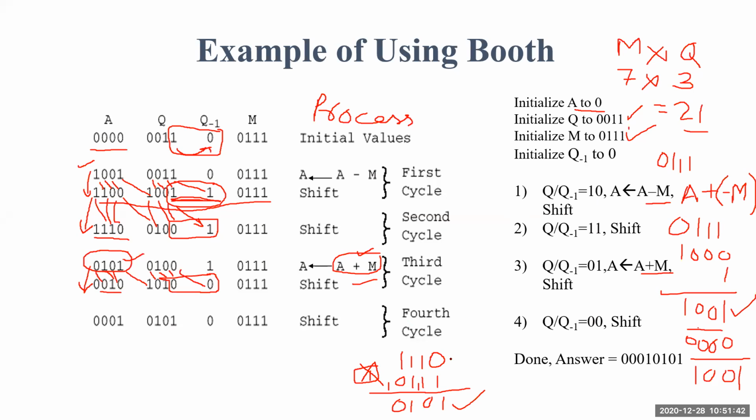So if it is 0 0, you should do the right shift for this accumulator. See now, this 0 is transferred to this new location of the accumulator. After that, 0 comes to this particular location, then 0 moves to this location, 1 comes to this location, and then the rightmost bit of the accumulator moves to the leftmost bit of the Q register. So that's why 0 comes over here, and the Q's bits move to the next locations, 1 and 0 0, and this will be my 1, and ultimately the 0 comes to this Q bit.